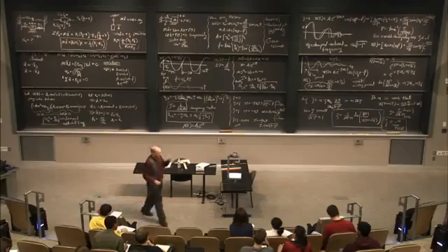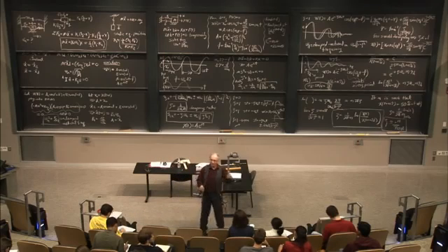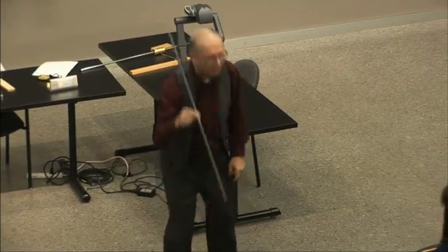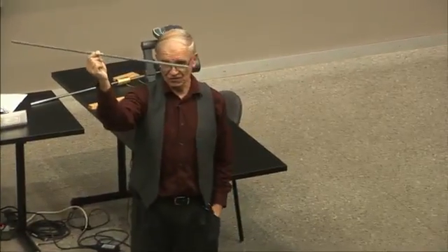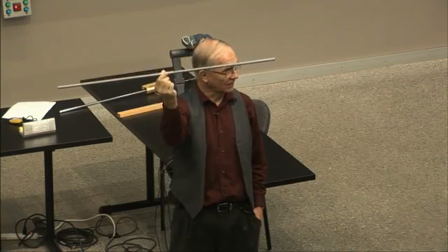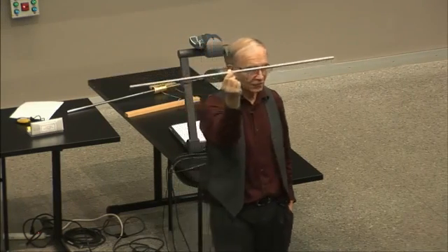Now I'll close by just saying one other thing. If something vibrates a lot, the damping's small. You need small damping for things to actually vibrate very much. This is vibrating. That high-pitched one, that's about 1 kilohertz. How many cycles do you think it's gone through to get down to 50% of that initial amplitude that you could hear? A few thousand? How much damping do you think this rod has? Really tiny, okay?